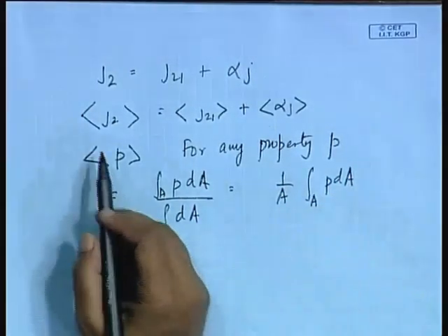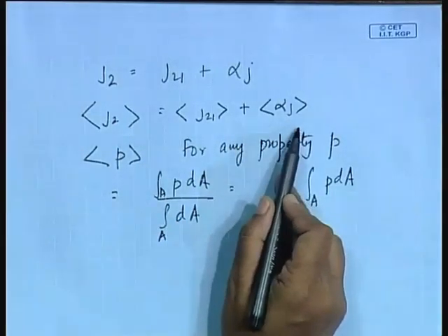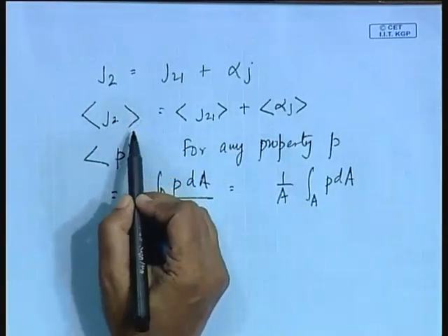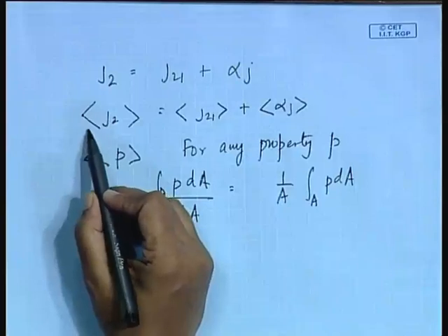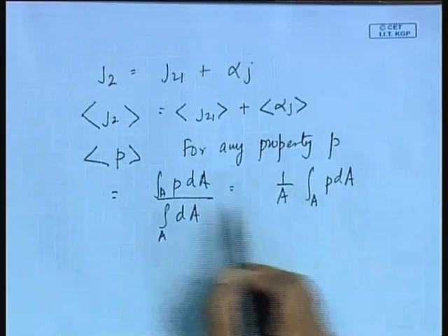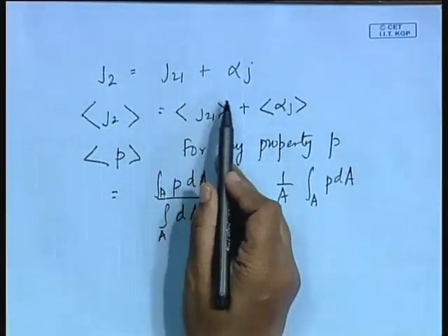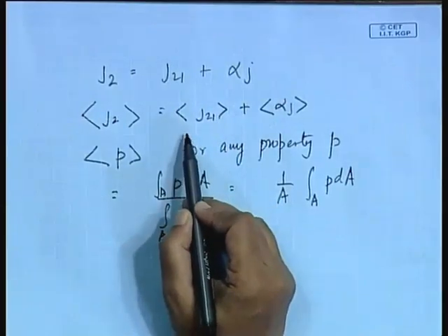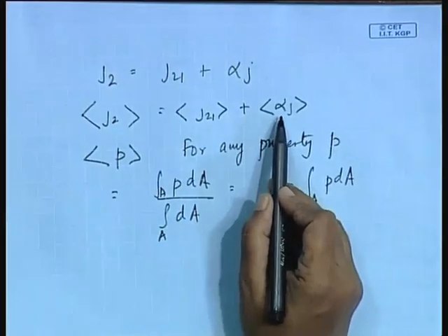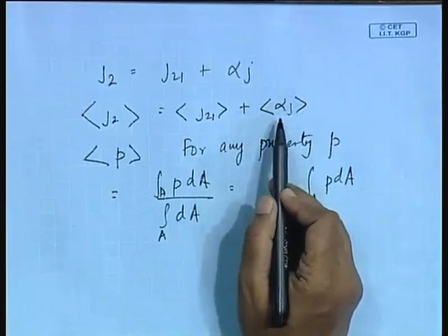Okay. So, you can very well understand that when I put these brackets across the individual terms of these expressions, this is the average volumetric flux of component 2 averaged over the entire cross section. This is nothing but integral J2 dA by A. This is the average drift flux averaged over the entire cross section, and this is the product of volumetric concentration and volumetric flux averaged over the entire cross section.